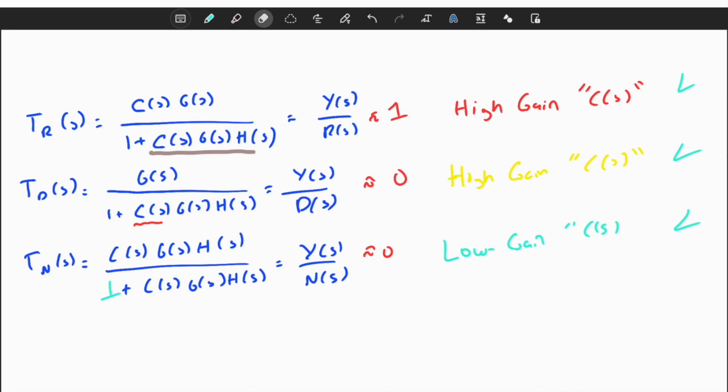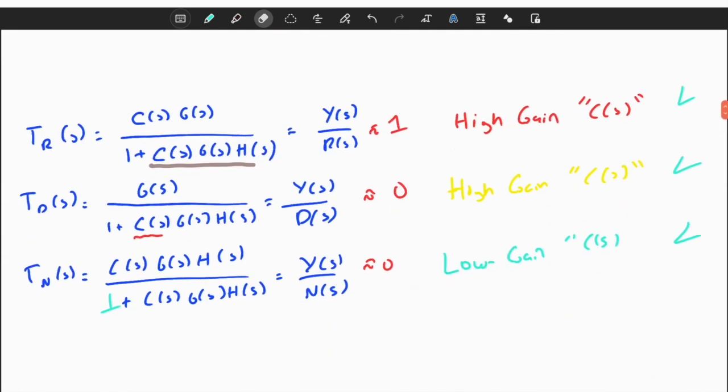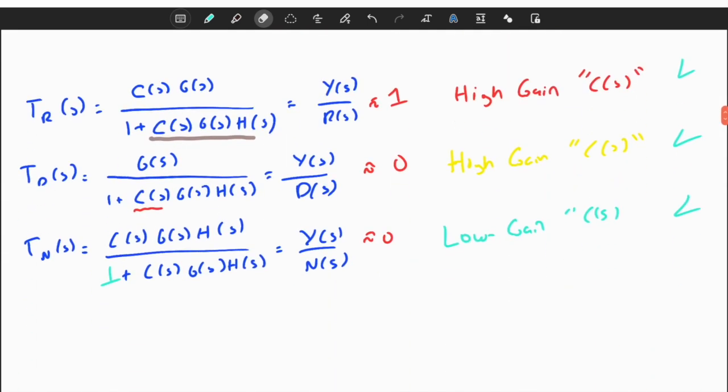It's one of the simplest control systems because it's single output and single input in terms of the control action here. Even if you go to multi-input, multi-output systems, you need to deal with this kind of trade-off, where you need to technically choose a middle path between using a high gain and low gain controller. If you go high gain, you will be terrible in terms of measurement noise rejection. If you go low gain, you will be terrible in terms of tracking and disturbance rejection.